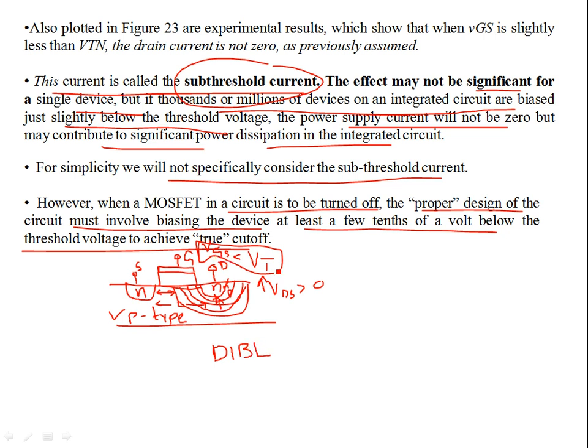So basically, by VDS you are increasing the depletion width and reducing the energy barrier, because the only way that the electrons can tunnel through from source to drain is the channel. But if you keep on increasing VDS, much greater than 0, the depletion width keeps on increasing as you reverse bias this PN region. So from the drain, you're inducing a lower barrier between source and drain,